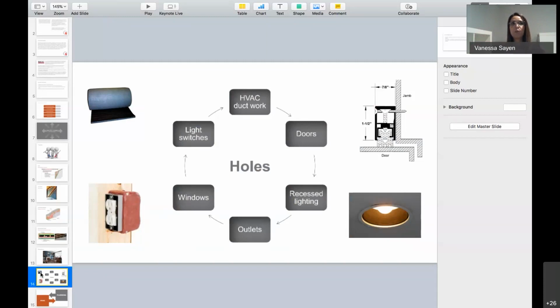So that's when we suggest using acoustic caulking to reduce the noise transmission. Also, weather stripping around doorways and windows can improve sound isolation and prevent sound leakage. And also take measures to prevent switch and outlet covers, HVAC grills, doors, light fixtures, and others from rattling. You can use putty or different types of materials. For instance, in home theater applications, you're going to see that a lot of our AV installers actually glue the screws in the air conditioning vents, so that prevents future rattles, and that could be very annoying.